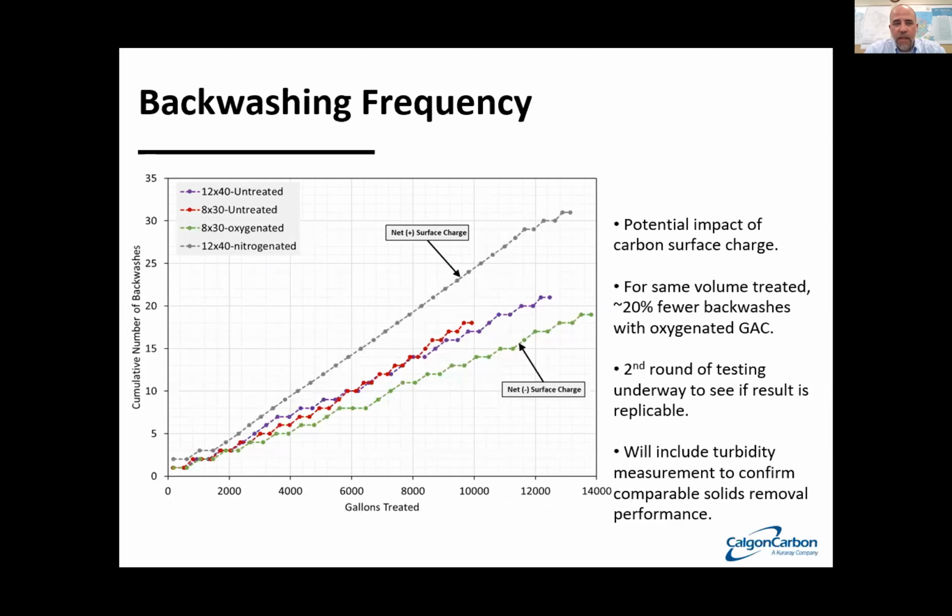So up until this point, the UCMR4 compounds, they're removable. That's great because we're looking at compounds that are recalcitrant. That's why they're making their way through the wastewater treatment system. They're making their way most likely through our bodies and into the wastewater as we are the vehicle for the contamination there. But this was a very interesting result here. And as a water treatment plant operator, operating a surface water facility where you're backwashing at a regular rate, this is an extremely valuable and I'd argue the most valuable conclusion out of the work.